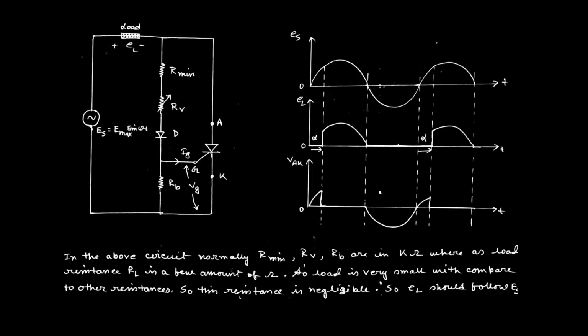And as per the normal behavior of the sine wave, when the wave goes beyond 180 degrees, the switch is in the reverse biasing condition, because after 180 degrees the polarity changes. It will be positive, it will be negative. Then the anode is negative with respect to the cathode, so the switch is under reverse biasing condition. At the same time, the current across the thyristor is 0. This is the normal commutation technique. Then the device will be in the off state automatically.